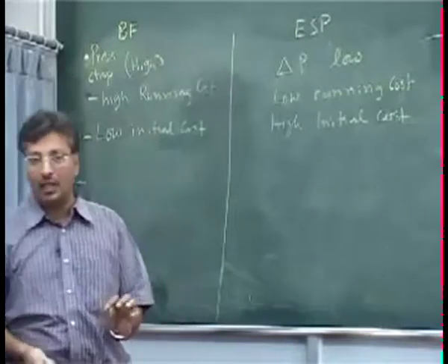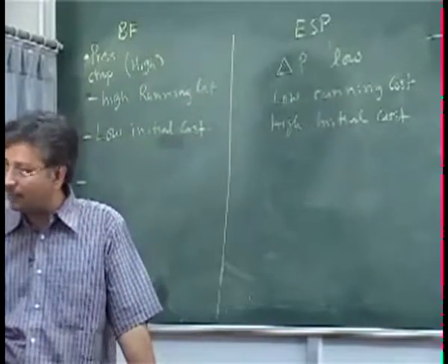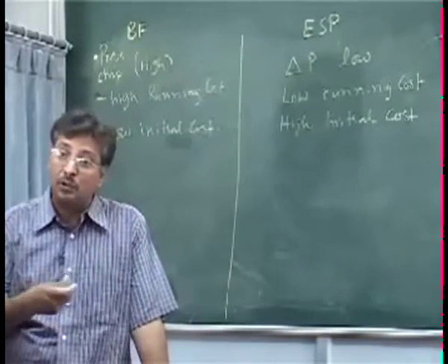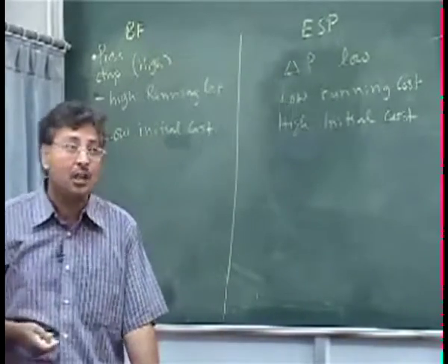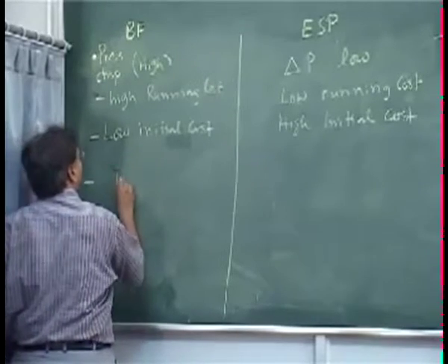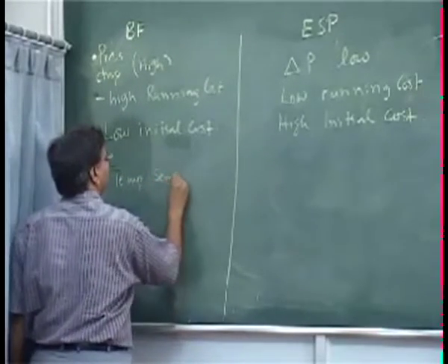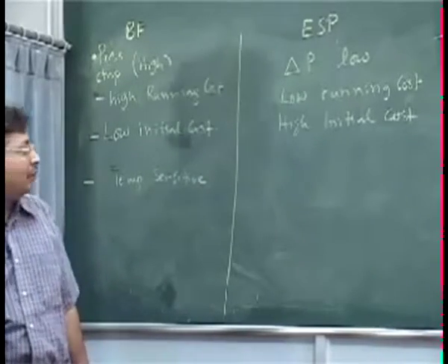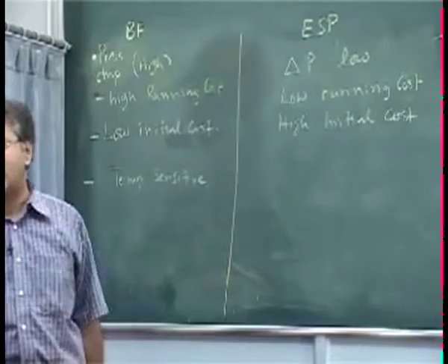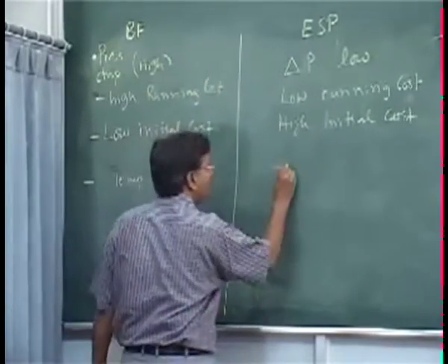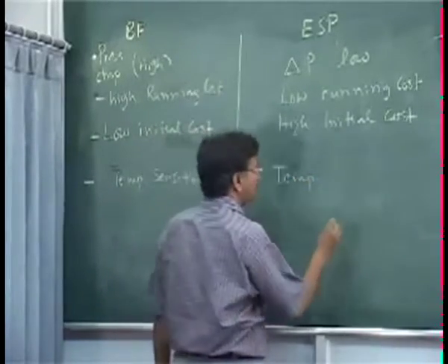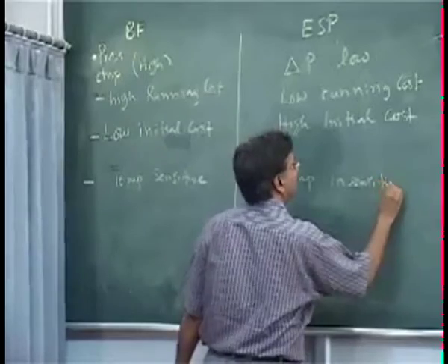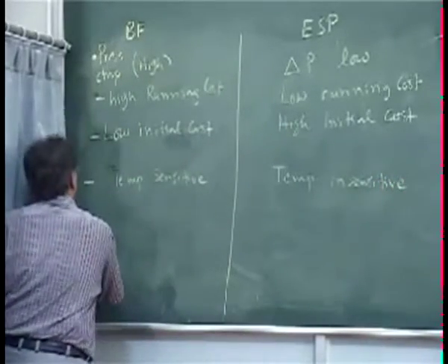Given the type of the bag and the temperature, can all bags or fabric adjust to all temperatures? No. If the cotton is there, for example, and the heat is very high, it may not be able to adjust to that. So the bag filter is temperature sensitive. Depending on the temperature of the gas you are dealing with, the quality of the filter medium and the fabric filter that we are using will change. The ESP is not so sensitive; it is temperature insensitive, if you like.